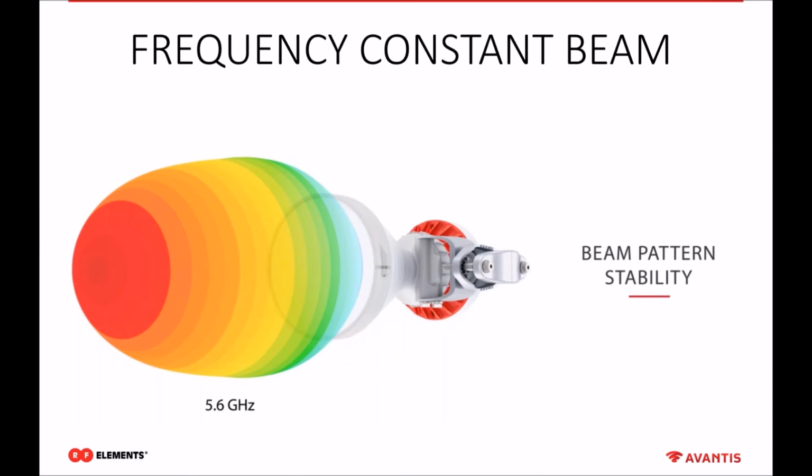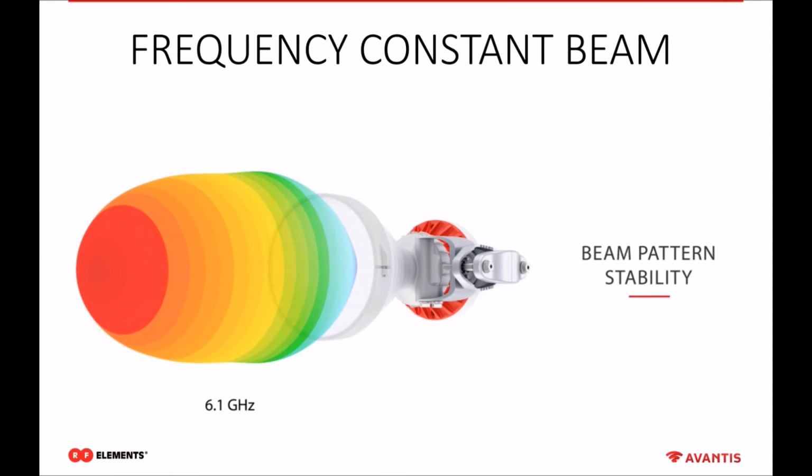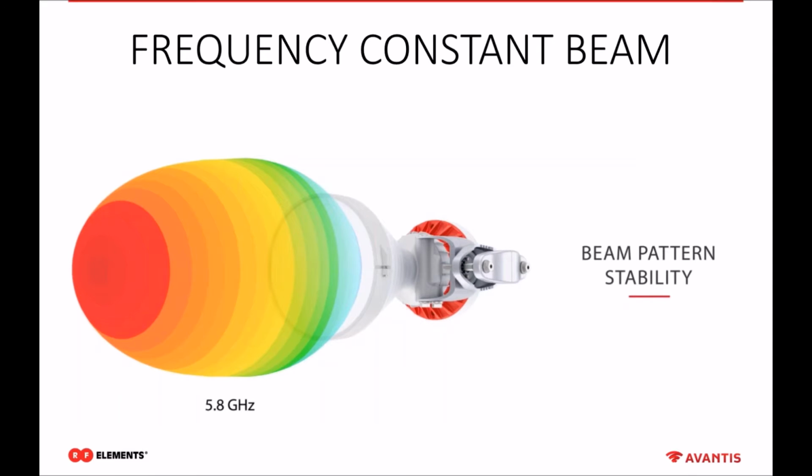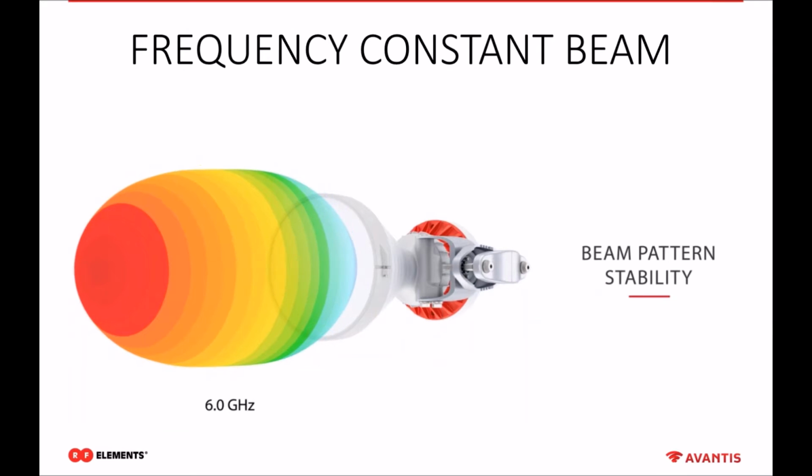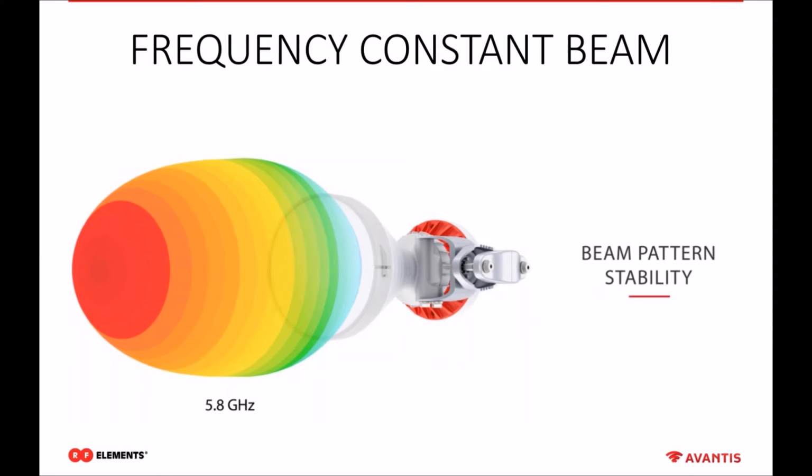But as time goes by, a new ISP will come to the same site, and that channel might not be the best available, so you decide to change the channel. And here, with a symmetrical sector antenna, there is no need to go up the tower again and try to find the position again, because the beam of the symmetrical sector antenna is very similar even if you change the frequency.